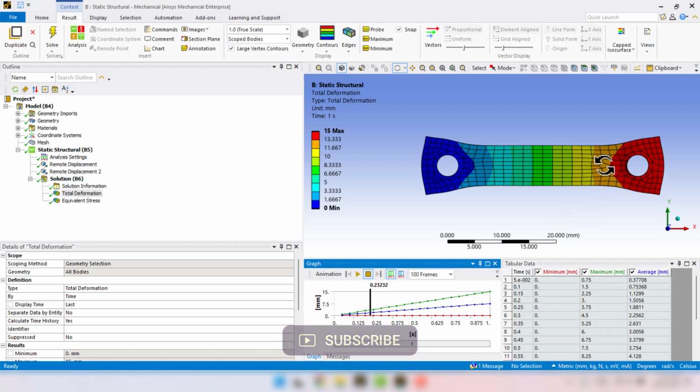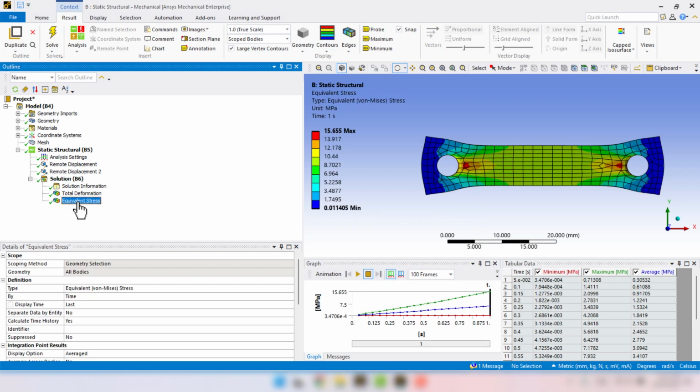Some elements around the holes are distorted, which means that applying excessive stretch can lead to numerical divergence. Now let's check the von Mises stress. The maximum stress appears in the x direction, which is reasonable. Next, let's add a twisting deformation to the sample.